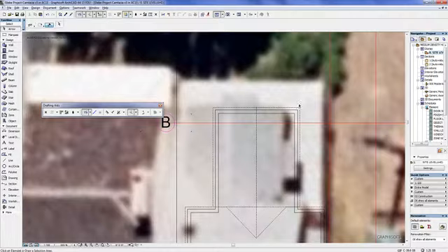Then we get to here, and now because the offset is active, it's asking us, well, do we want to offset inward by the direction that we're moving our cursor, or can we offset outward? Because we can do that too. So we can offset inward. So we just have to push the cursor in the inward direction, then press tab and offset by 100. Okay. All right.